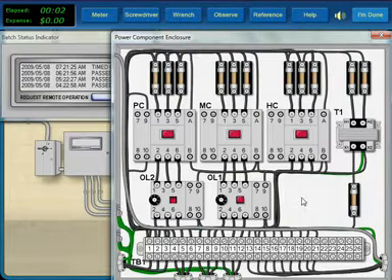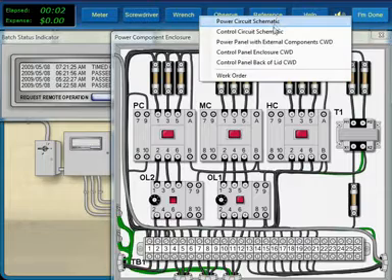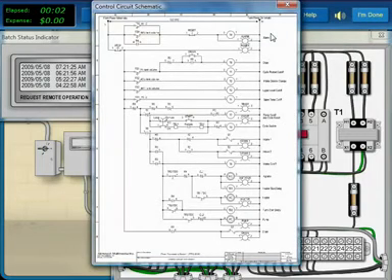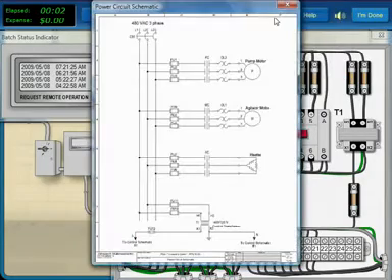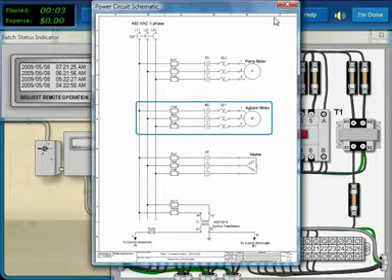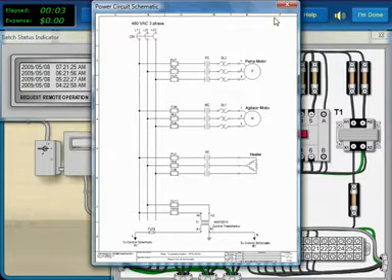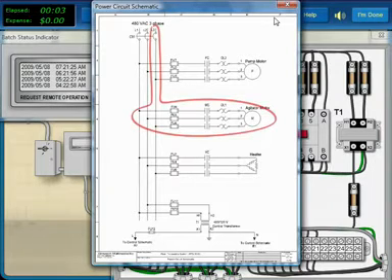The observations tell us a lot about the problem area. The control portion of the circuit can be excluded because it works as expected. In the power circuit, we can exclude the 2 phases which supply the control circuit. Also, since the overload trips, we know that there is current in at least 1 phase of the agitator circuit. Therefore, the problem area is confined to the agitator power circuit and the 3rd supply phase.